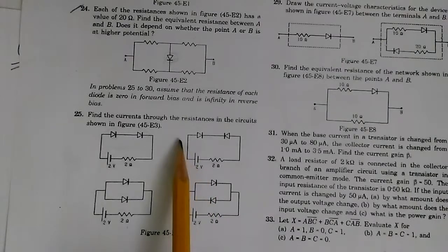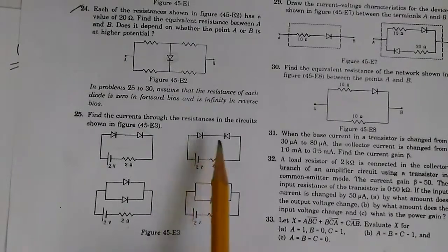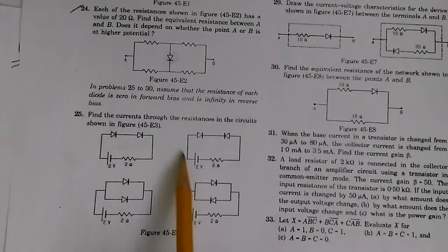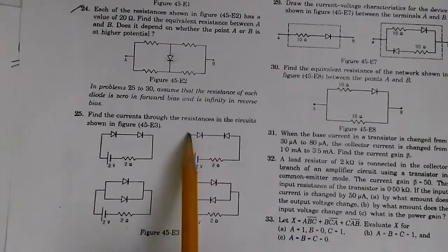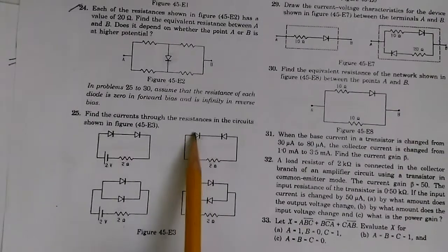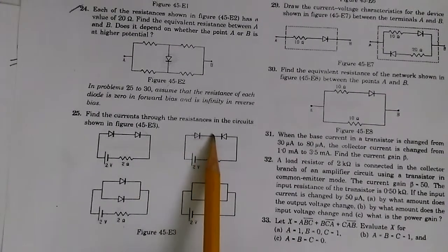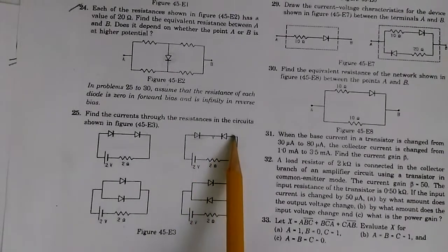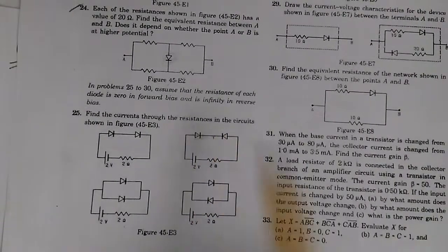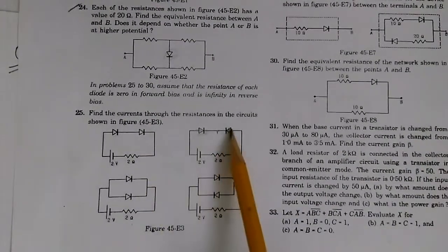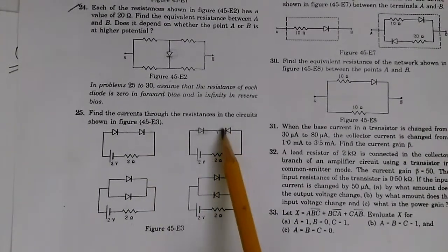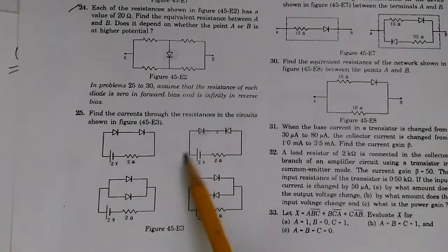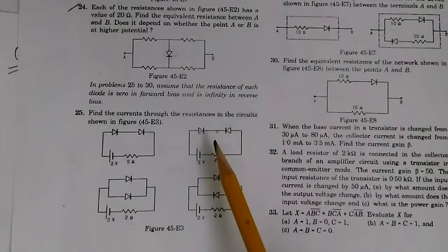In this one, one diode is in the forward direction, the other is in the reverse direction. So let's say this is forward bias, so we can just remove this diode and replace it with a wire. But there is a positive voltage here and there is a negative voltage here. So this means this diode is reverse bias. When this diode is reverse bias, this circuit acts like an open circuit, and therefore the current in this circuit is 0. That is part 2.